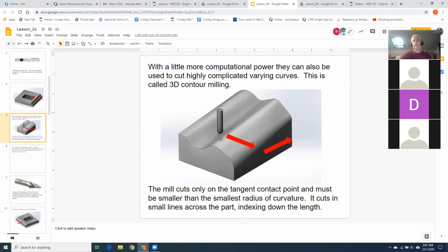And again, if you're doing something like this, maybe you want to come in with a big tool first and just lop off a whole bunch of metal, get you close, a kind of close shape, then come back in with your fine tool and do a cleanup. So that might be a good way to do a mold or a complex contour like an airfoil, something like that.